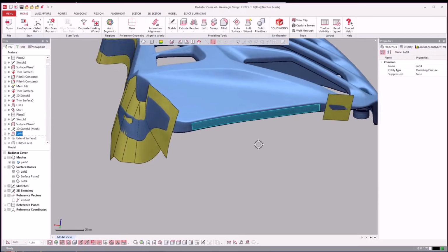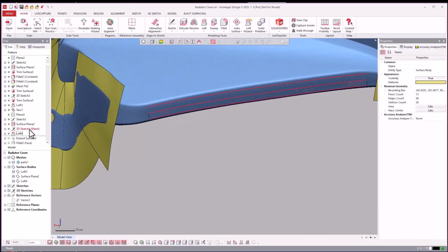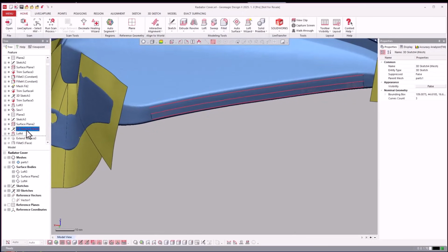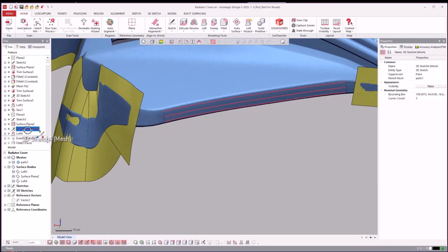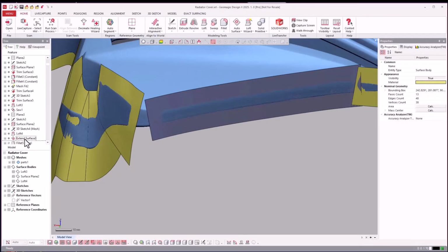We did one of those vertical lofts. That's what I like to call them, right? Or we drew the 3 lines and lofted it down. That's a good way to do it. Like, that's one way. I tend to, you'll notice me, if I model it, I'll do a boundary fit surface where I draw a square patch on it. I don't know. It just depends on how people think. So they did what I call the vertical, or maybe it should be called the horizontal loft. I don't know. And then go ahead and extend it.